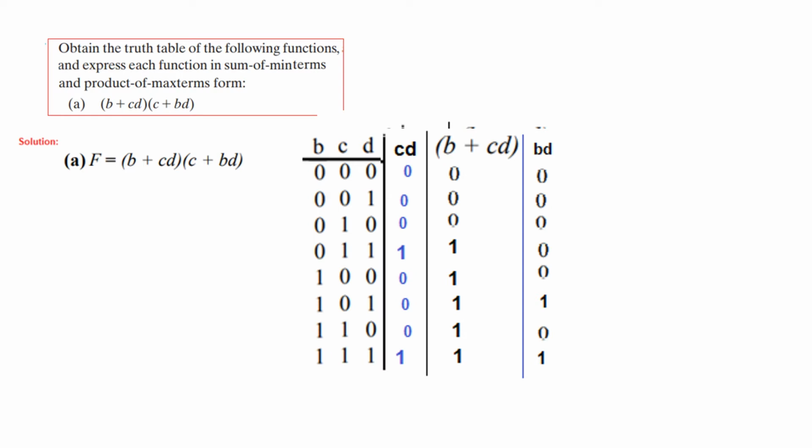So now you can see this is 0, so up to this point there cannot be any 1. This is 1, so there is a possibility of getting a 1, and we have to look for D now. So CD is 1 here, B1 D1, so we write a 1 here. Similarly B1 D1, we write a 1 here, and the remaining we fill with zeros.